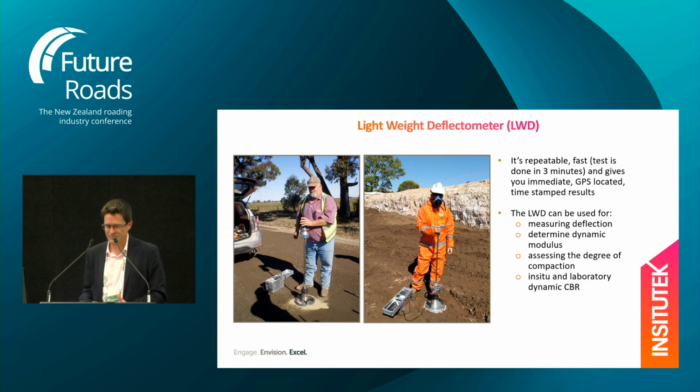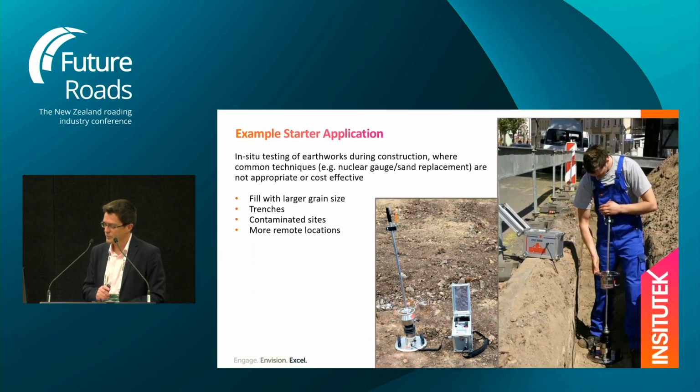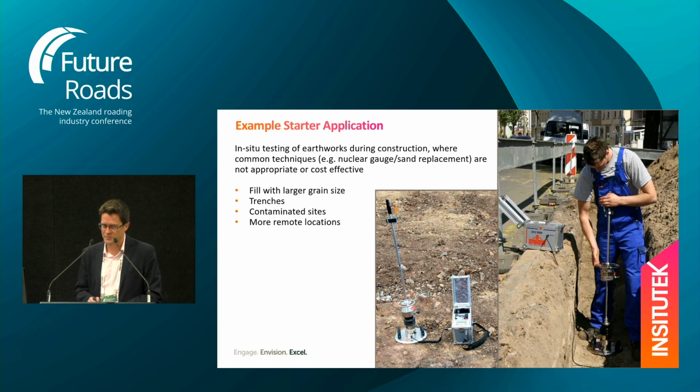It's fast, 3 minutes per test. We've also got high levels of repeatability, so that's important. We can also get an indication of the level of compaction of the material, and we can also work with larger grain size material.